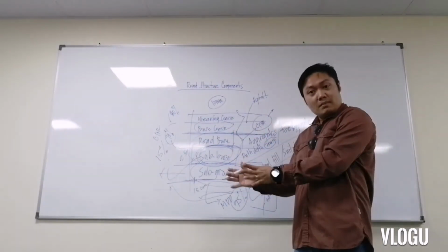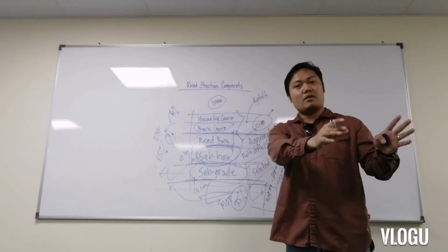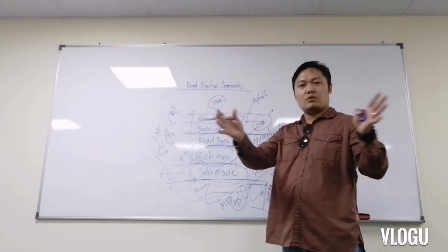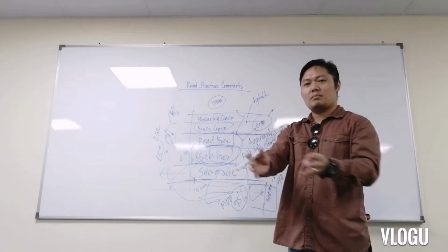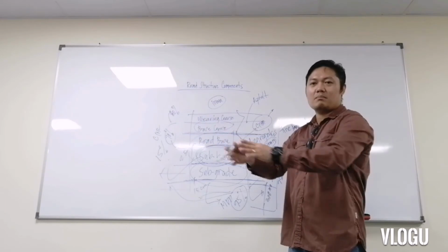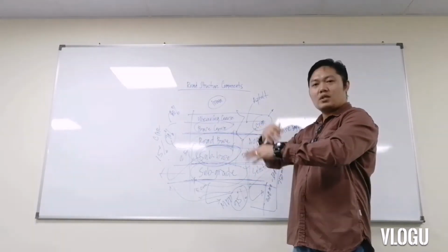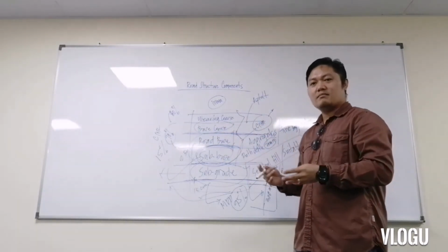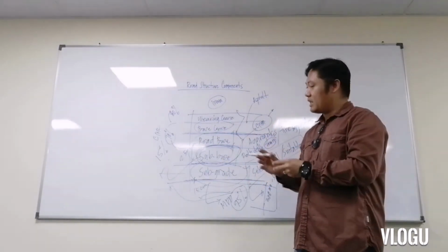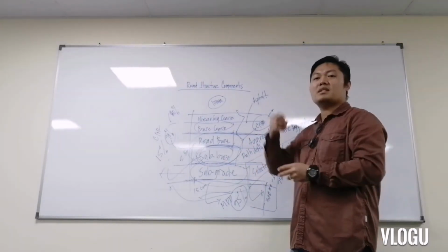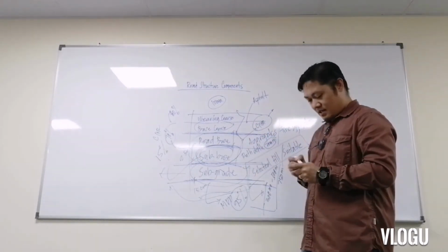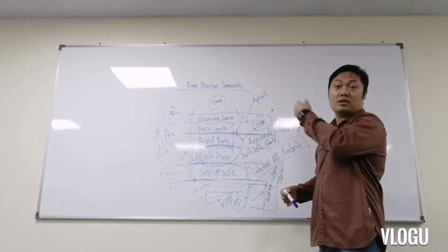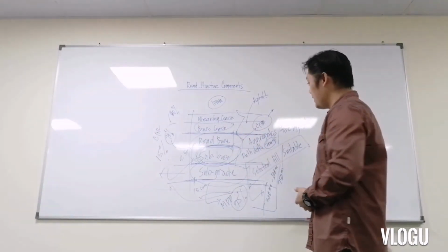So the recycled asphalt pavement comes from the existing road asphalt from other areas where it is being recycled. It is removed from the existing old asphalt roads and sent to the processing plant, where we crush all the asphalt and reprocess it. Fifteen percent of this quantity of recycled asphalt will be mixed into the new road asphalt. That is the sustainability program of any country.